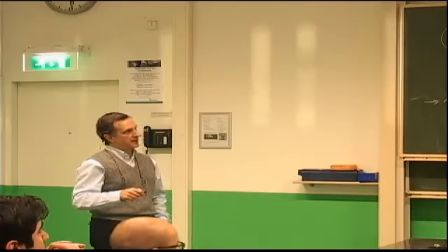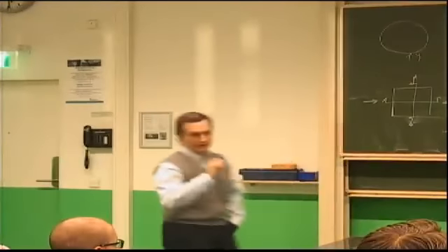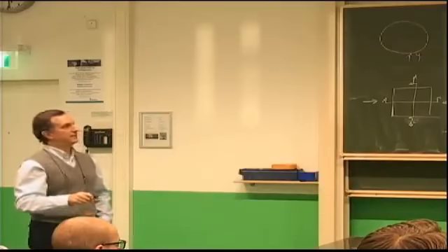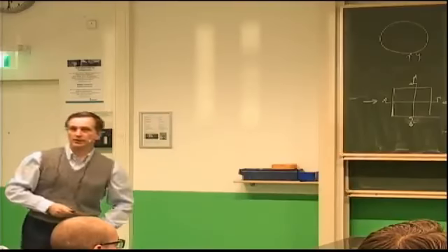So I say I need to increase the thickness of my composite by a factor 1.2 to the 1/3. And that is 1.063, or I need to increase it by 6.3%. So we'll stop here, but first you'll have to tell me why. How I came up with this. I say I want the composite, which had 20% lower buckling load, to have a thickness that is given by this quantity, 1.2 to the 1/3.